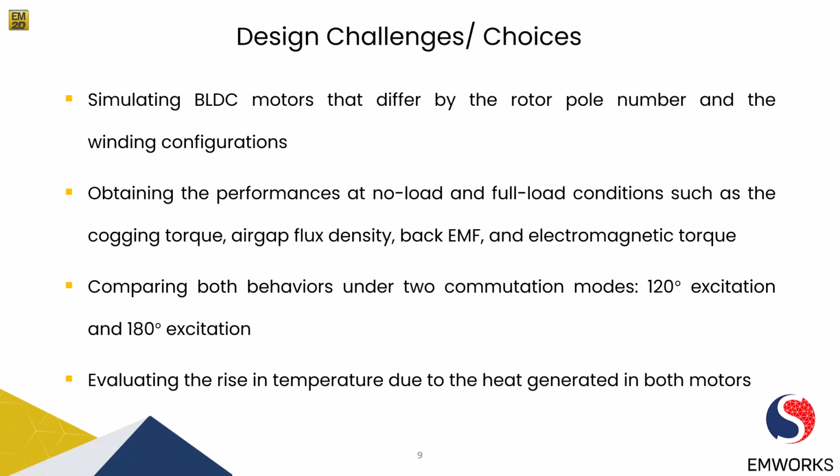Also, once we have the model ready, we need to obtain its performance at no load and full load conditions and get the parameters such as electromagnetic torque, back EMF, cogging torque, and the saturation areas in the rotor core or the magnet core, and the direction of flux. So there are many other different parameters that need to be analyzed.